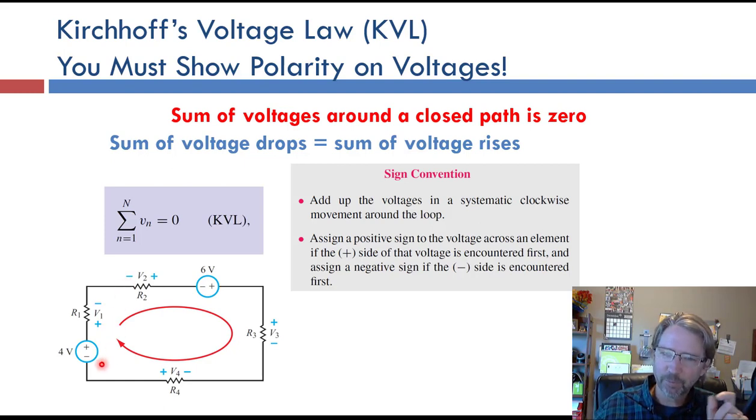The reason I used the other one before is because when you write these things, here we're subtracting the 4 volt because we're coming up as we come through the loop, where this is actually supplying energy, but we're subtracting. Anyway, it matches our passive sign convention this way too. So we would subtract 4 volts, we would add V1, subtract V2, subtract V6.